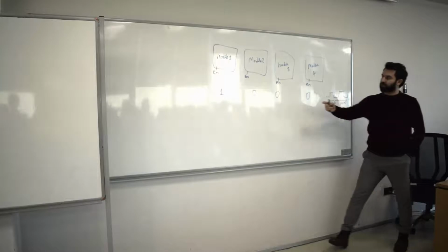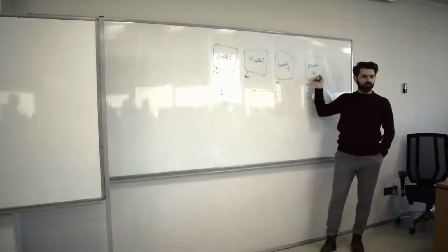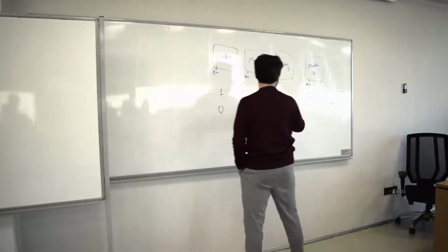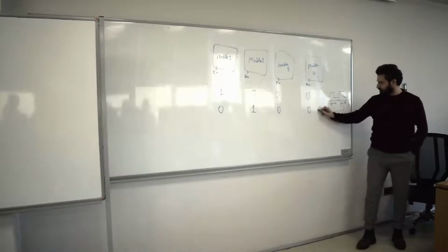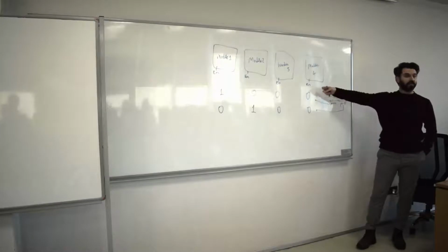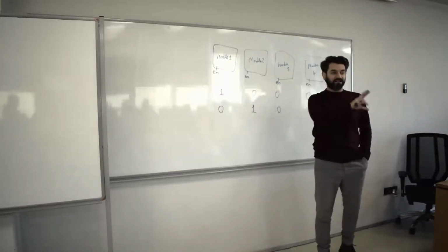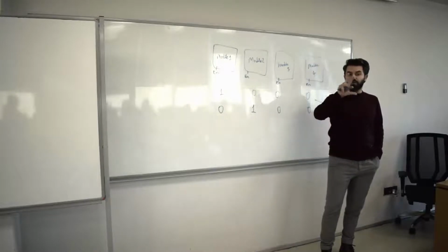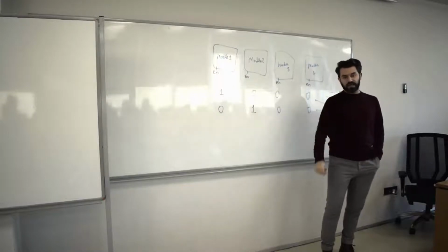In the next period, module 2 is now turned on. This one is turned off, and off. That means in the second period, I'm going to send 0 for module 1, 1 for module 2, 0 for module 3, and 0 for module 4. That's the first period, and the second period. You will use that kind of architecture in your CPU design, because in your CPU design there are many hardware blocks. Some of the blocks have to be enabled, some of them have to be disabled. Otherwise, the hardware that needs to be disabled will operate on the data and corrupt it.